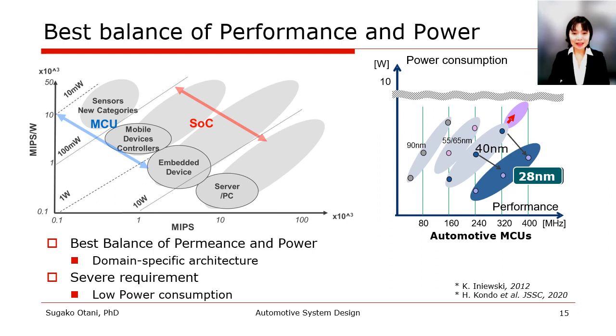The main strategy to achieve this is to employ dedicated hardware. We will see various dedicated hardware in this tutorial. The balance point between power consumption and performance varies depending on the application. But in the embedded field, low power consumption is an absolute requirement. Power limits are constrained by thermal dissipation cost, package, and the power environment.